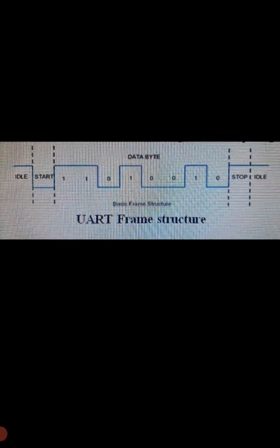The features of UART0 are 16-byte receiver and transmitter FIFOs, that means first in first out, a built-in fractional baud rate generator with auto-bauding capabilities, software flow control, and the TXEN bit, the transmit enable bit, in the registers.